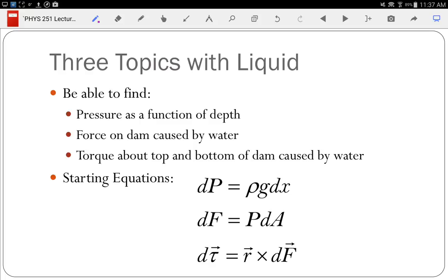And so then I had my pressure was a function of height, and my variable was height, and the width was constant. So this dA became the width times dy for the height. And so while it is a dA, an integral over area, you can immediately, just in your head, do the integral over one of those 2 dimensions and come down to that.